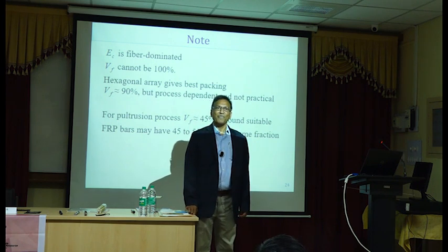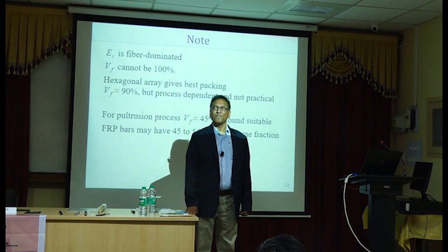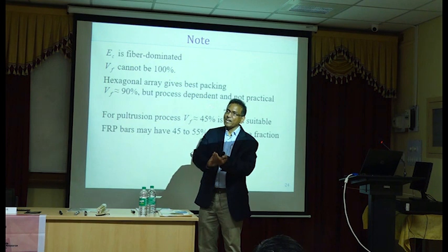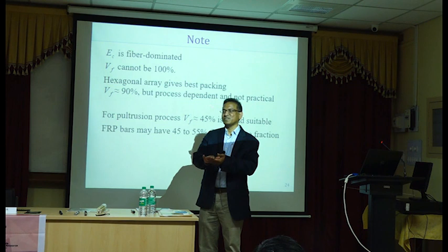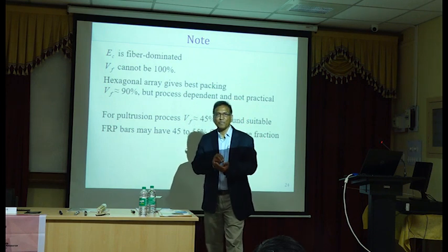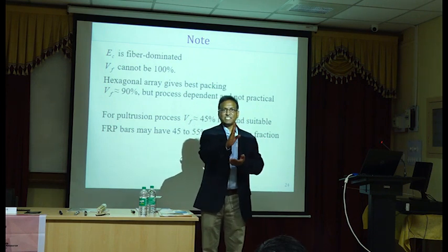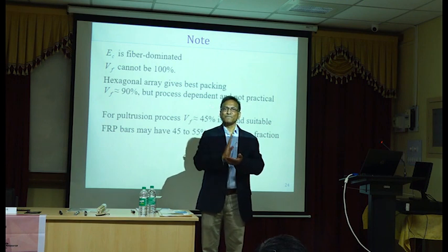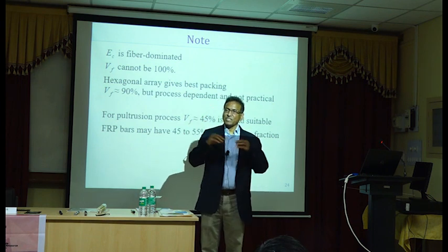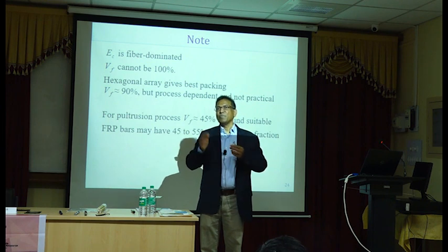Stability is good, but I would like an even better one. Yes, resin is wet. When it is wet, it is resin. When it's dry, it's matrix. But my question is, what is the main function of a matrix? Stiffness is good. I like that. Anything else? Bonding is good, but I'm looking for something else. Confinement is good, because if there is any compressive stress, there will be no micro buckling.